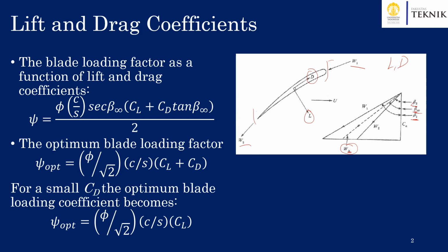And as we know, we can write down the lift coefficient, or CL, as a function of the lift force divided by 0.5 multiplied with density, the relative velocity, or the mean relative velocity, multiplied with A, the span-wise area of the airfoil. And A, or the blade area, is the product of the chord, or C, which we will use later on, and the span, or small l, of the airfoil.